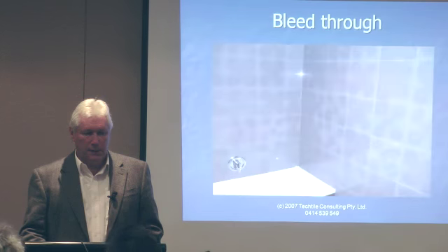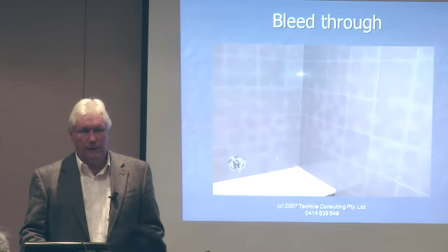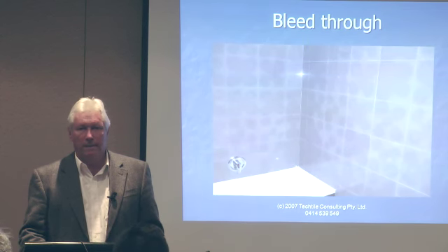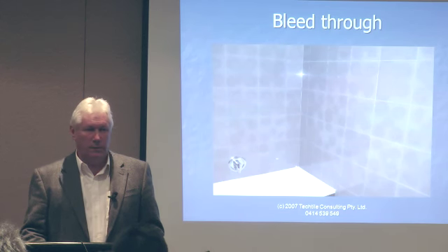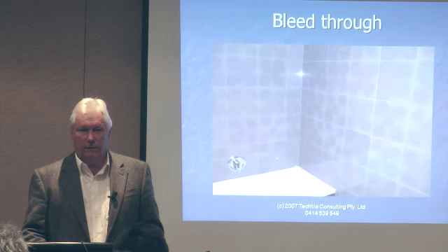But just to look at some of these, for instance, in this case, the adhesive that was used on the back of the stone was a cement-based adhesive. It was mixed with water. It didn't have certain other things in it. Nothing was done to the stone before it was laid. These tilers put the tiles on with 5 dots of adhesive on the back of it. That was fine. They managed to complete 80 bathrooms before the problem really started to become evident.